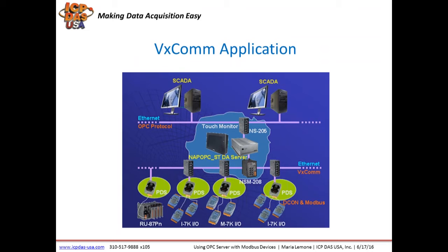NAPOPC Server supports communication protocol conversion applications, so you can convert one protocol to another, like Modbus RTU to Modbus TCP, and you can use that with NAPOPC Server for communication with legacy type equipment.